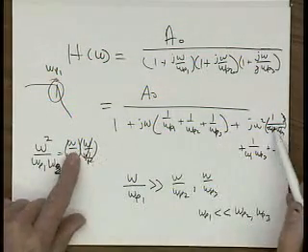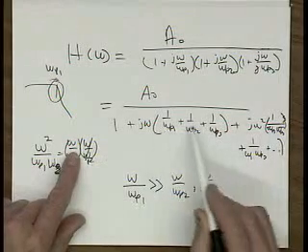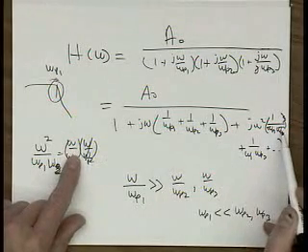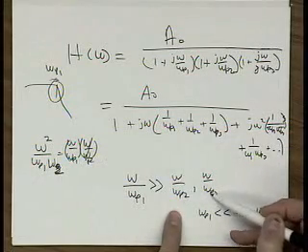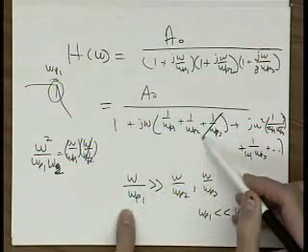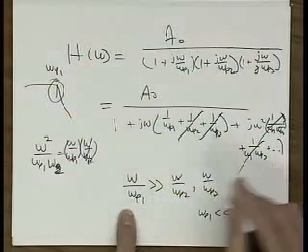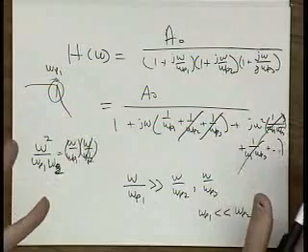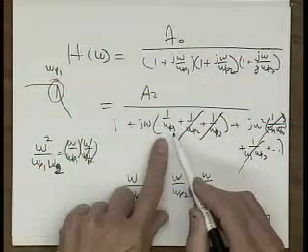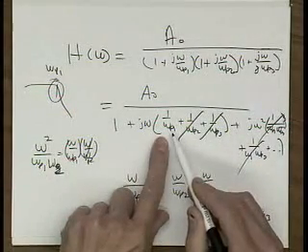That'll make all these terms small relative to these terms, because you always have one term that's really small. And since omega over omega p2 and omega over omega p3 are much smaller than omega over omega p1, these are all small. So we can argue that what you end up with in a multipole response is just that the lowest frequency pole will be important.